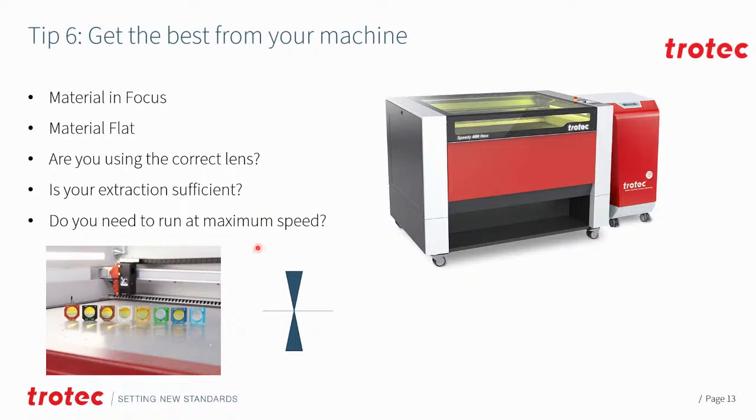The final thing to consider is, do you need to run the machine at maximum speed? So if you think when the laser head is firing across the material, especially on machines like the 400, where we're over 4 meters a second now, it's got to pulse on and off extremely fast. And you can still get a very good result, but you can also find that if you just reduce the speed slightly, it will still give you some improvements depending on the actual material that you're working with. So somewhere, depending on obviously the machine and the actual speed, I would still be probably over a meter a second, but it's worth just doing a little bit of experimentation to see if it actually helps bring up some of the data from your engraving.